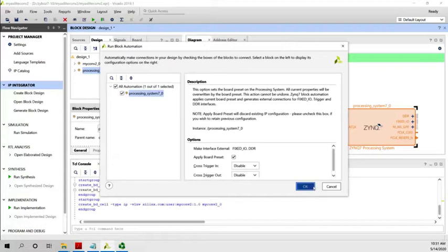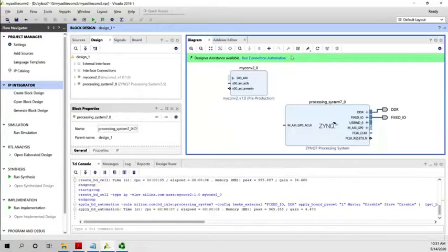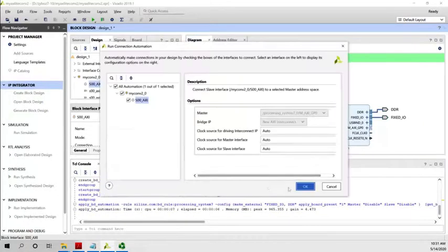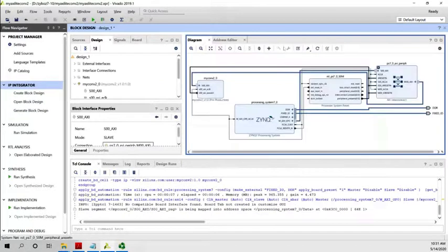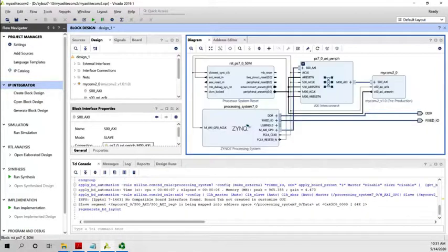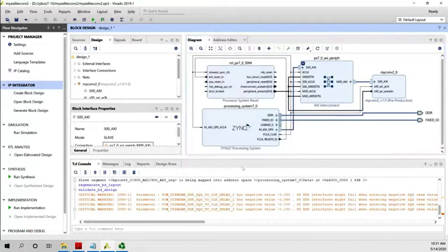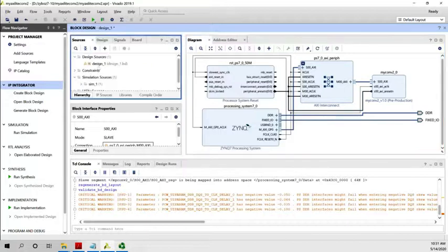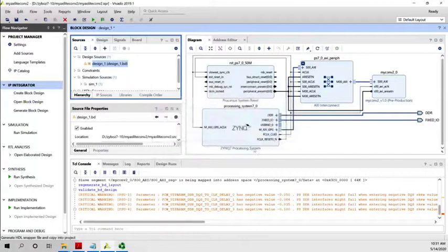And then this is just click and click. It's even simpler than the second tutorial, because in the second tutorial we needed to include extra IOs. Here we don't, because your peripheral is only communicating with the AXI-PS. We reorder the blocks, and then we validate, just in case something might be wrong. We go to sources. Once everything is ready, what do we do? We create the HDL wrapper.